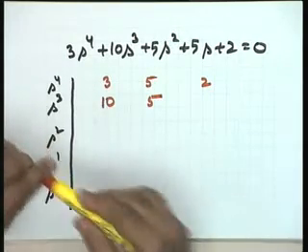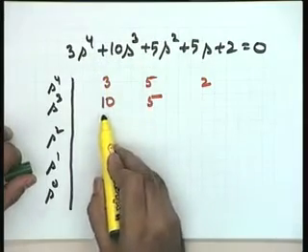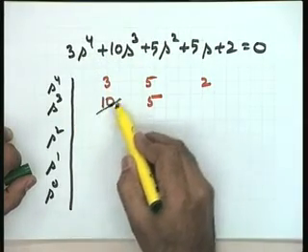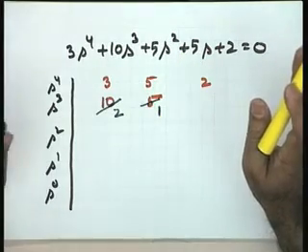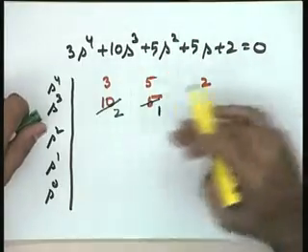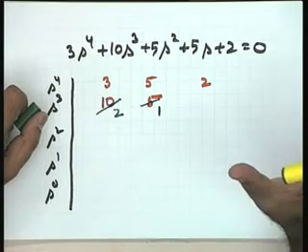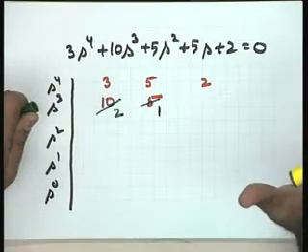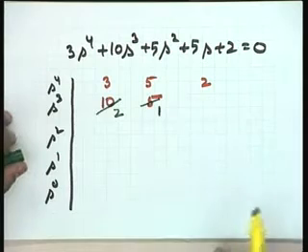Now, one change let me make over here, there is no problem there. Since in this particular case a complete row is divisible by 5, I can do that without changing my conclusion on the stability of the system. So, please see that multiplication or division of a complete row by a positive constant will not change the conclusion of stability. You may do that if it helps you in calculations, that is all. Naturally, the lower the value, the quicker the calculation. So, let me put it this way.